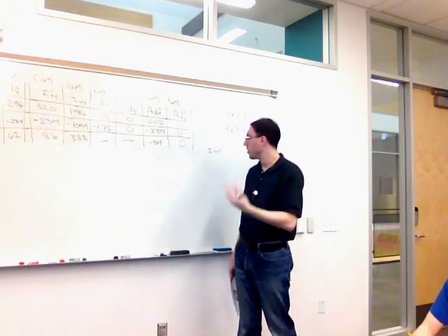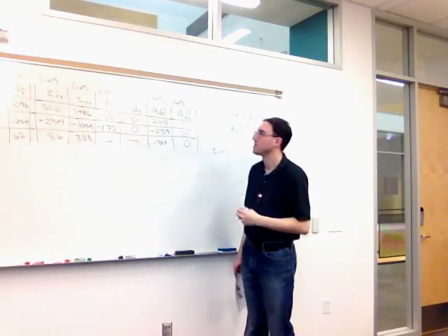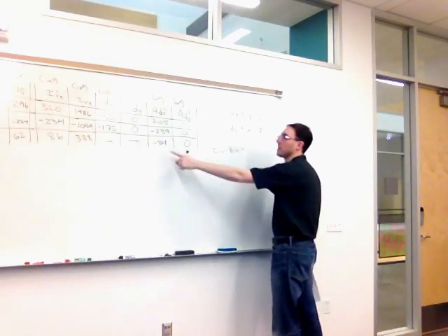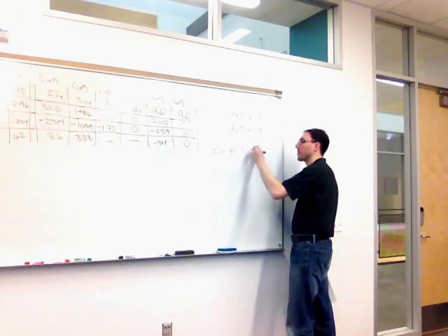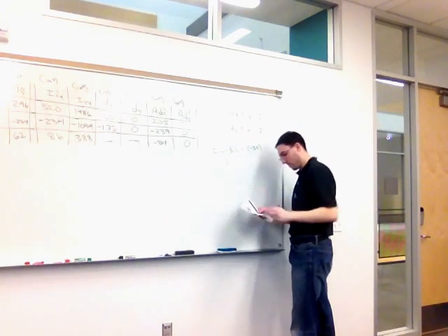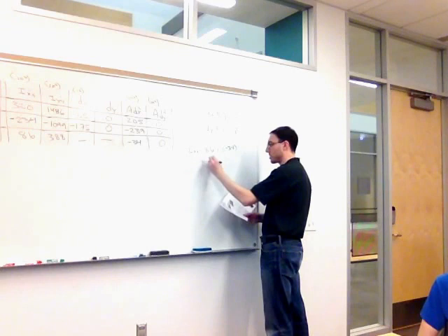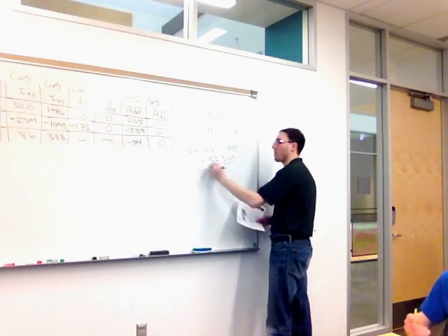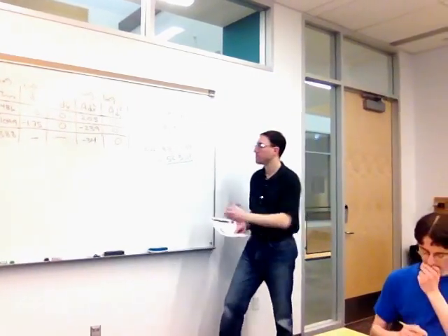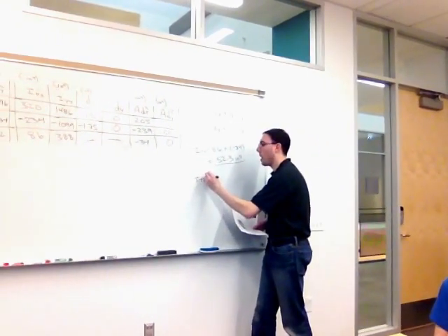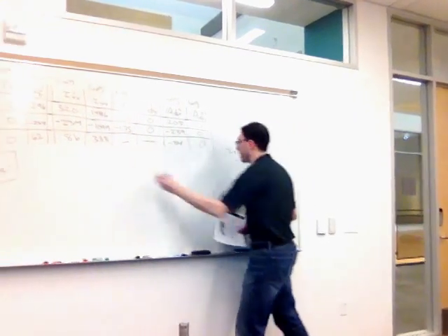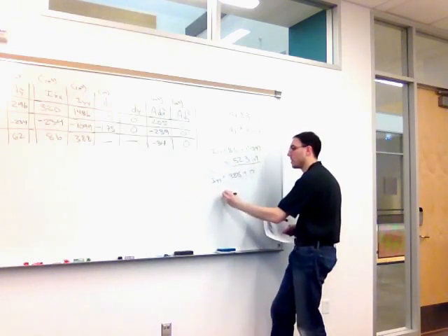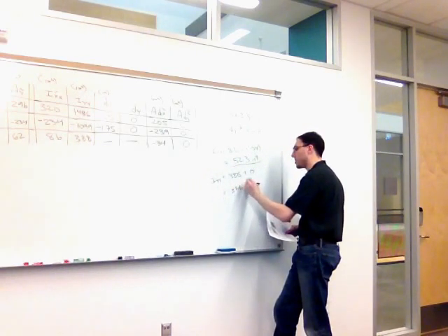Finally, we can find the total inertia of the shape about its own x-axis, or centroidal x-axis, is 86 plus the Adx squared terms, negative 34. So that total inertia is, with proper rounding here, 52.3 inches to the 4th power. For Iyy, we get this total of 388 plus this total of 0, and we get 388 inches to the 4th power.